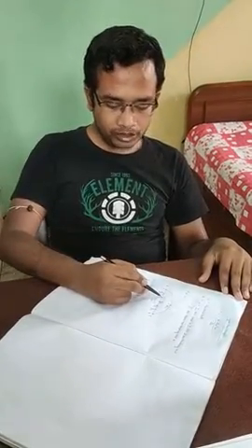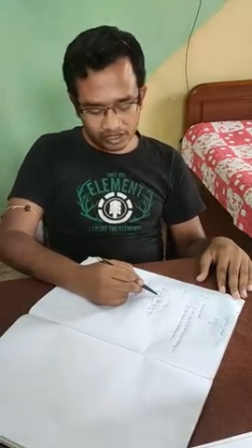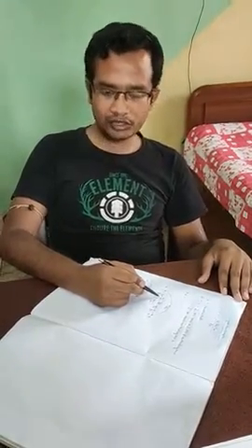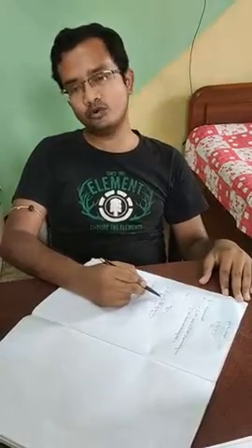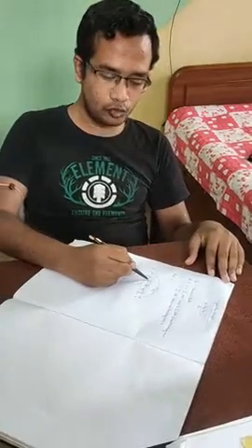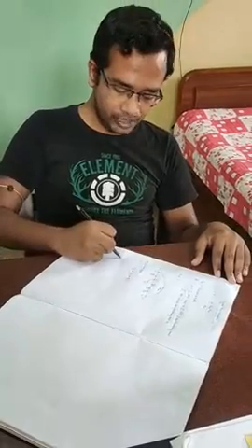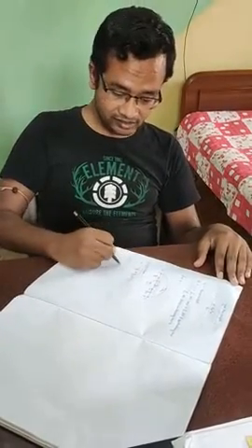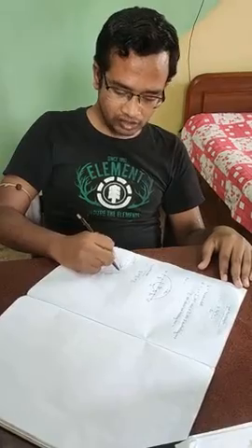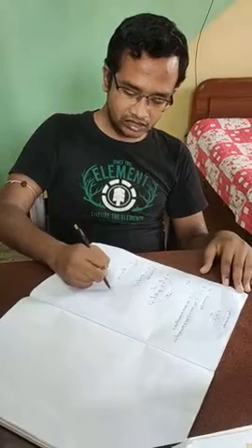The basic condition of being a loop is to start from a node and end at the same node, and in the whole path no other node will repeat twice. So let's start from node 2. Node 2, travel here to node 3, then again return back to node 2. This formation is a loop. So loop L1 in this case is G2 times minus H1, which is minus G2 H1.